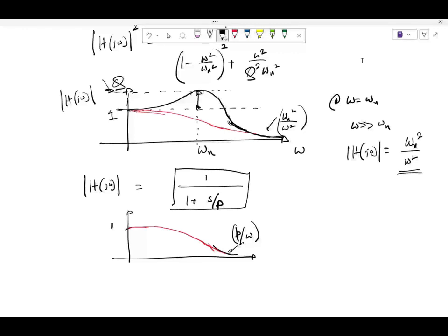Underdamped, right? Which means that in the underdamped condition, we will never be able to model it as a first order response. Correct? What about critically damped? Q equal to 1, right? Where Q equal to 1 means it's better modeled, but it will not peak per se.